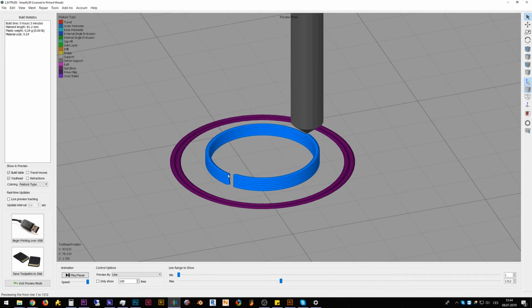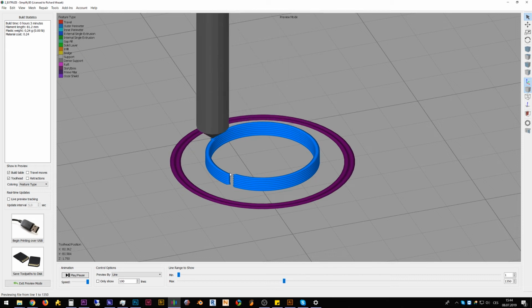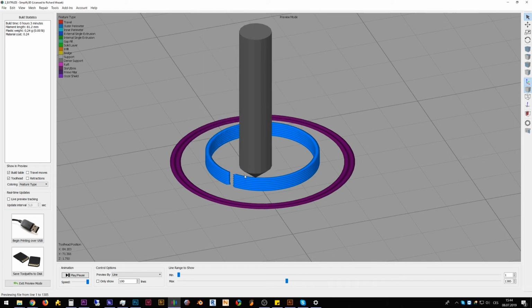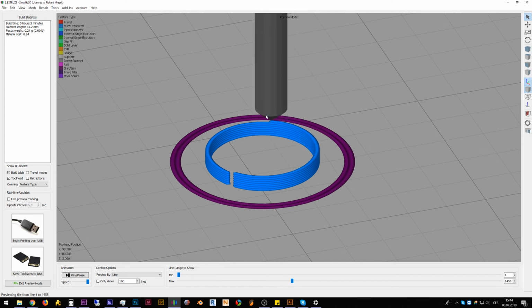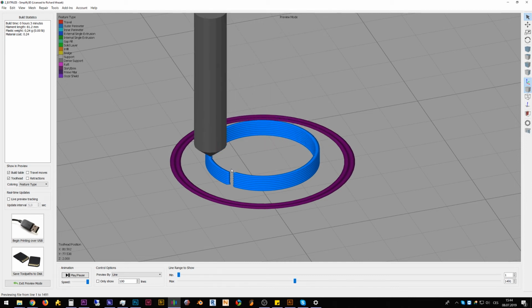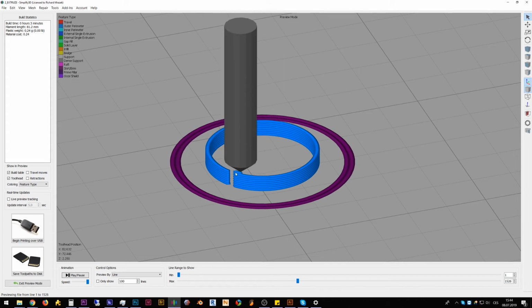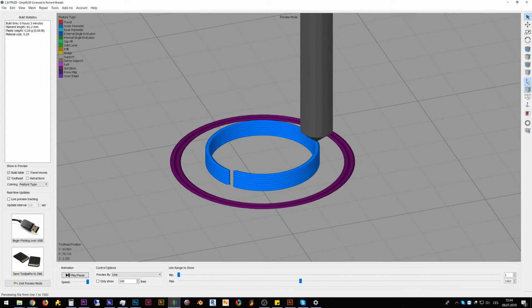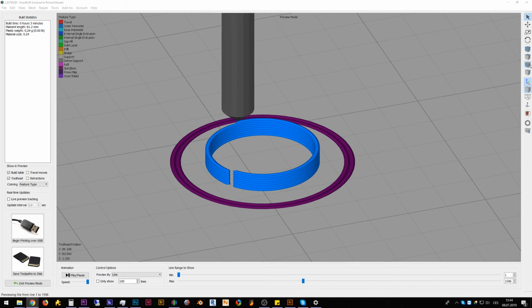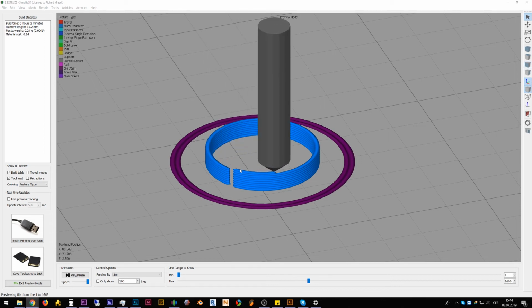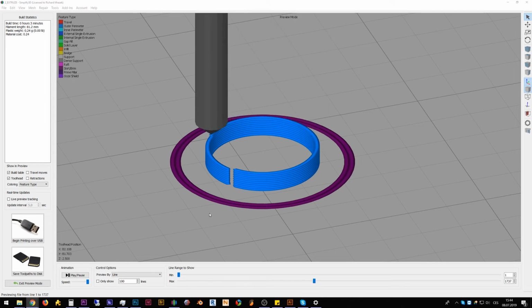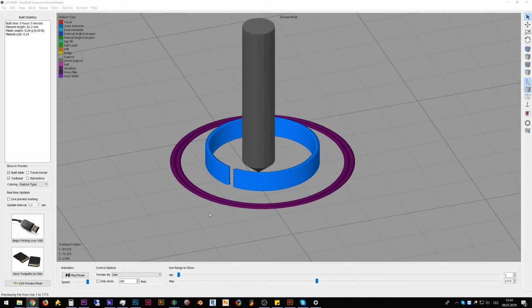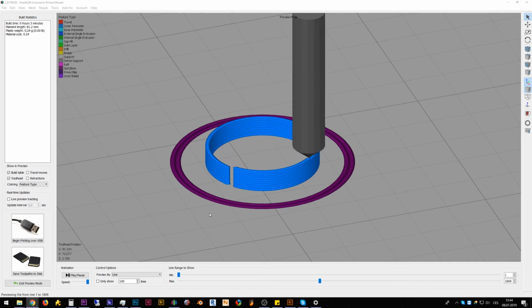It means the seam will be stronger, and if there is some amount of filament in the nozzle, it will be wiped. It will be wiped on this wipe movement under the already printed perimeter.